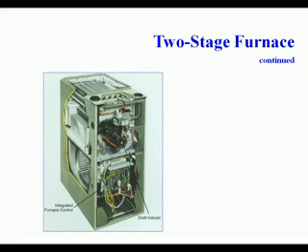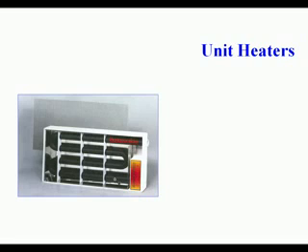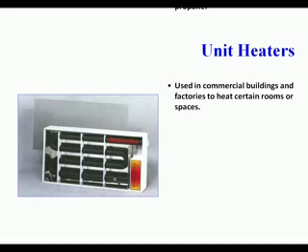A variable speed indoor blower motor creates a more consistent airflow, allowing the air filter to trap more impurities, thus improving indoor air quality. The two-stage modulating furnace can provide rates between 40% and 100% of total capacity. A solid-state integrated furnace control initiates and manages the sequence of events. The unit automatically chooses the most efficient blower speed.